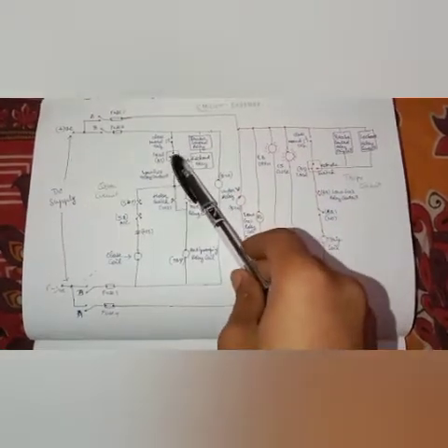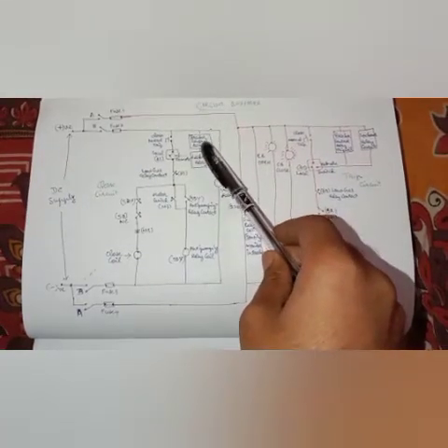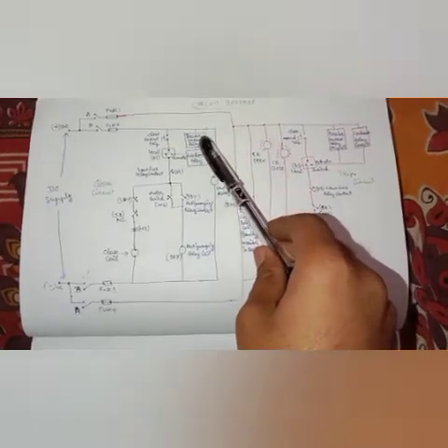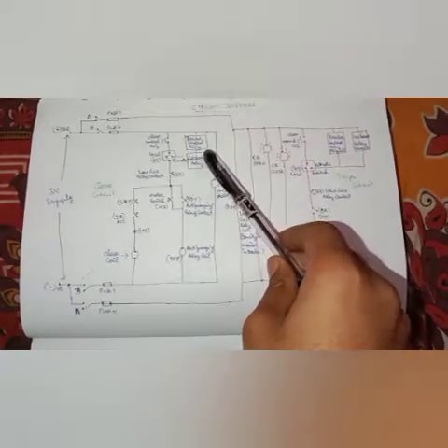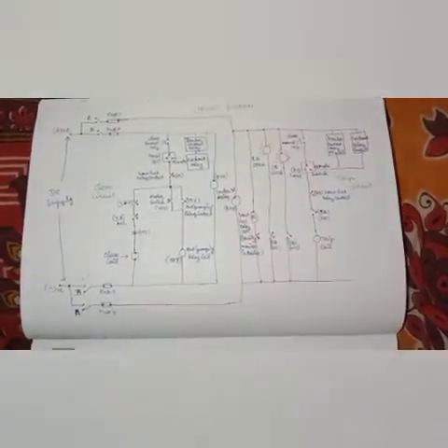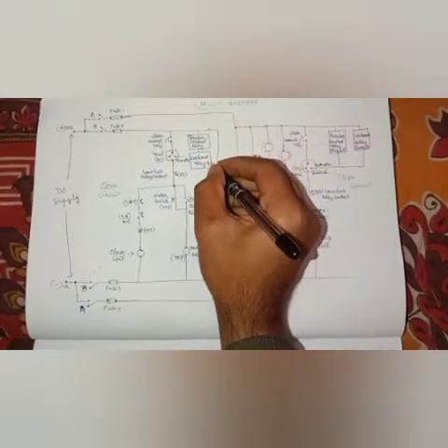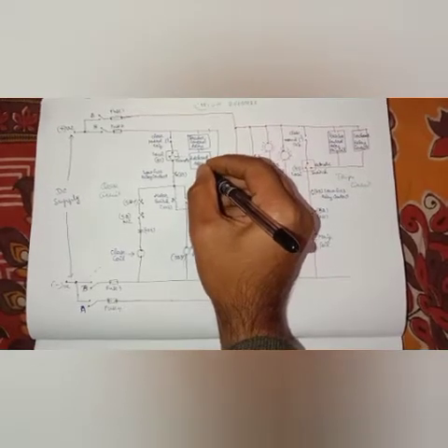Here in the case of remote, the breaker control relay, which means from the SCADA HMI, the closing operation will be done and the command will be given, and it will check the lockout relay, which means the 86 relay. Normally this lockout relay is connected with all the protection relays.